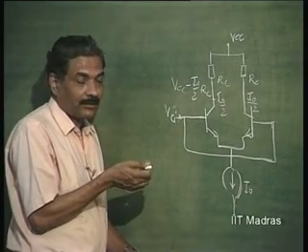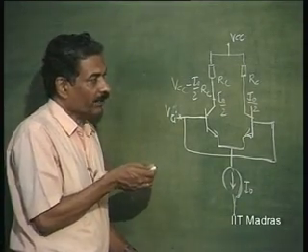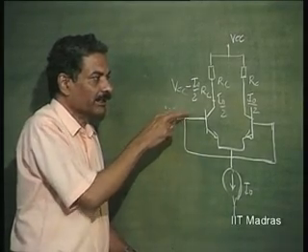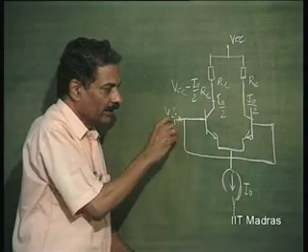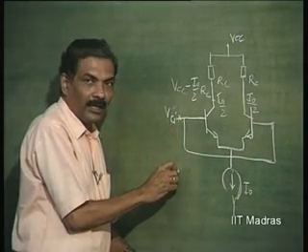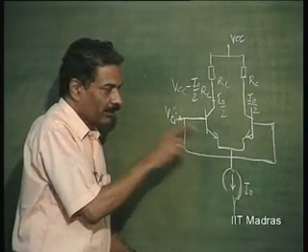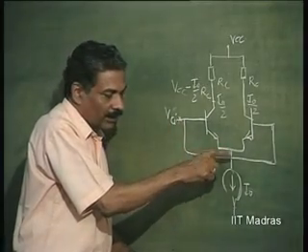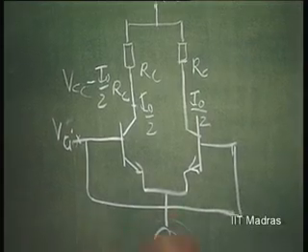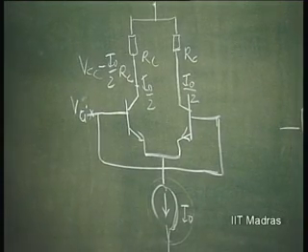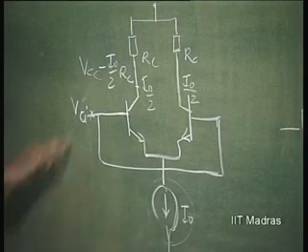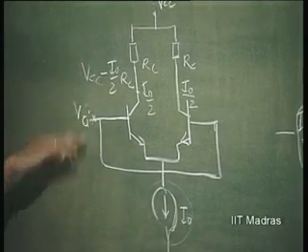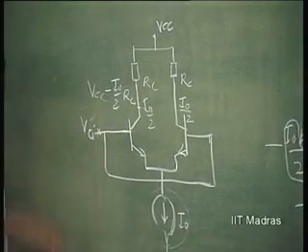Right. So, this kind of thing can be prevented if you take care to see that this common mode voltage does not exceed this. Here on the other side, this voltage can go down and this voltage will follow this, Vc minus V gamma will be the voltage here, and at that time this current source should remain still active. So, that is the condition. So, there is a limit on Vc max as well as Vc minimum as far as the input stage is concerned.